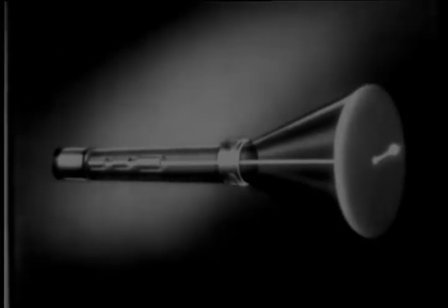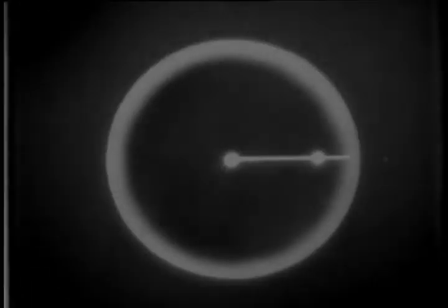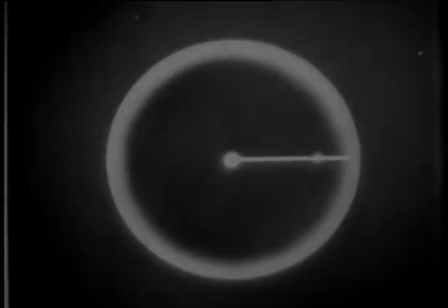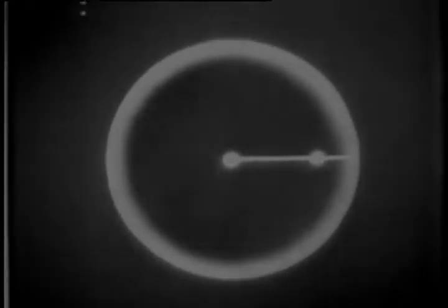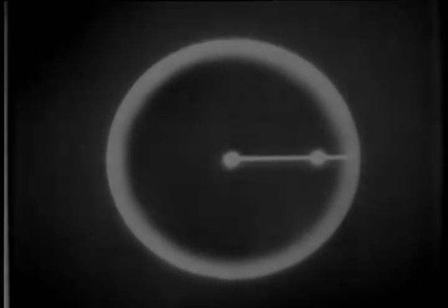Since each time the antenna is pointing at the target, there are several thousand pulses sent out and several thousand echoes return, the increase in electron flow at that point happens so fast that it forms a steady glow of light on the baseline at the range of the target.